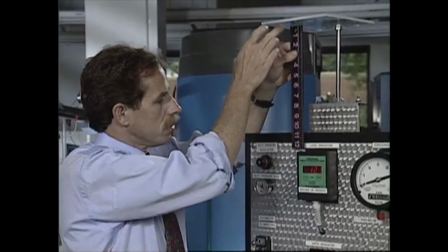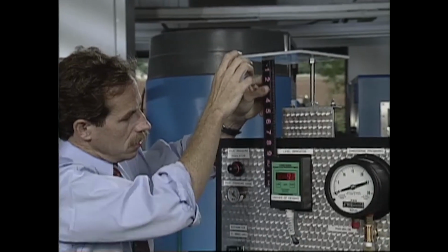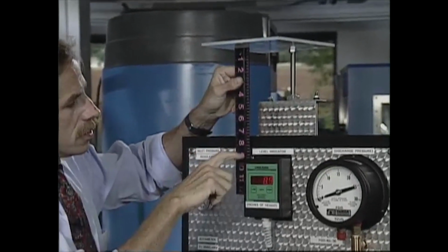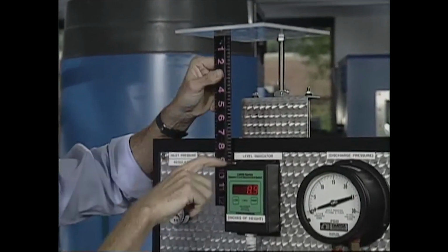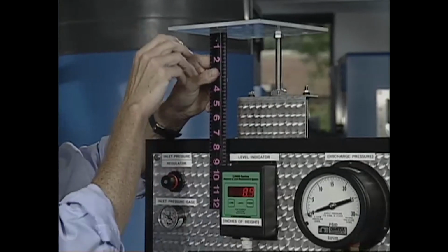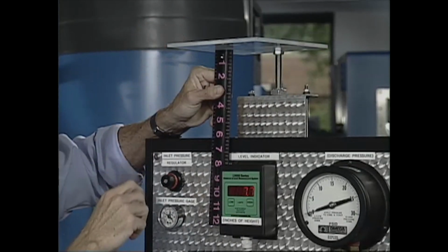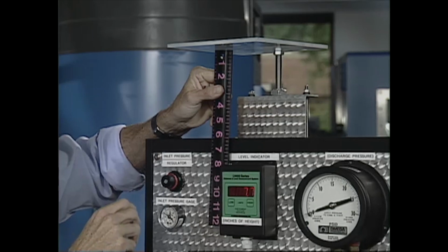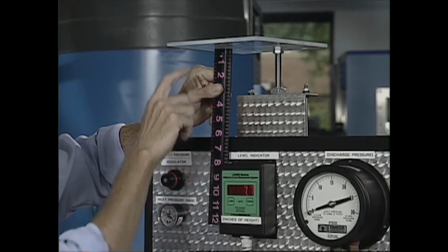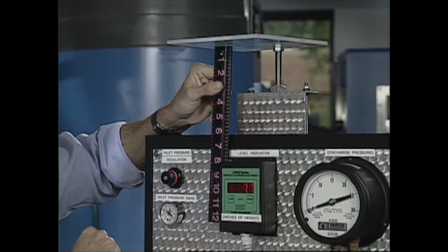As I move the plexiglass plate here, you can see that the distance is shorter, so it takes less time for the wave to go up to the plexiglass and back. Now, the beauty of this method is that you don't need direct contact between the sensor and the object you're trying to measure. Acoustic time of flight techniques can also be used for making distance measurements in fluids such as water. Now, the speed of sound in seawater, for example, is much faster than air. It's about 1,500 meters per second.